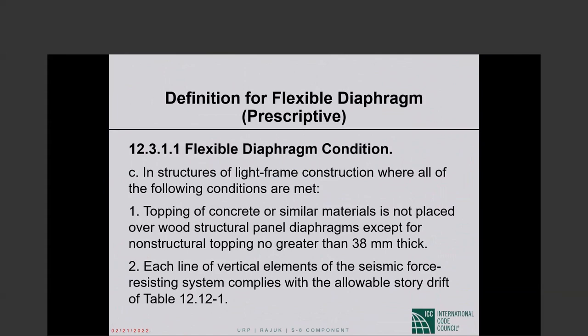Topping of concrete or similar material is not placed over wood structural panel diaphragms. No concrete topping, except for non-structural topping, no greater than 1.5 inches. Okay, there can be a non-structural topping.